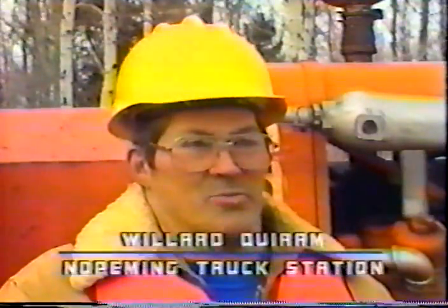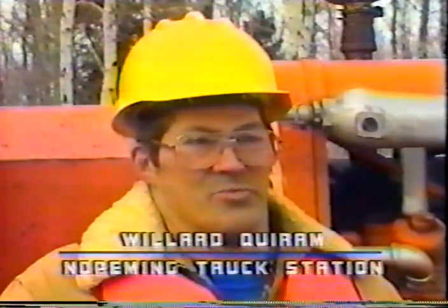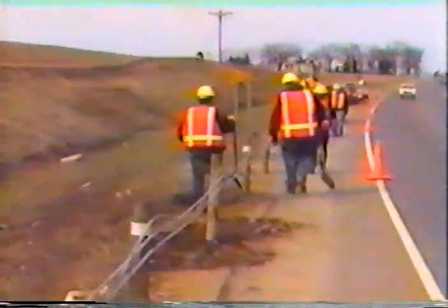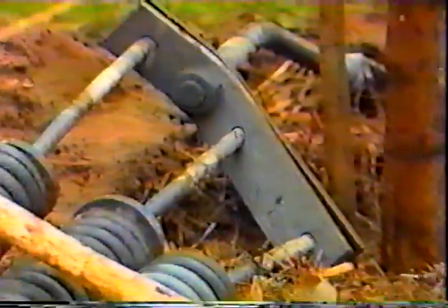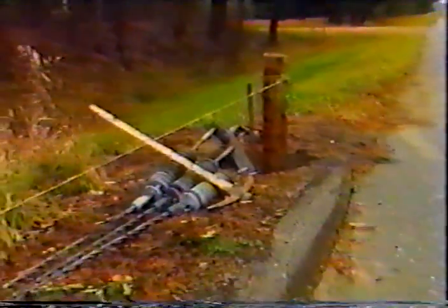If it's been weakened by a previous accident and not repaired, and I guess that's why you'd have to make sure it's repaired in that same structure that it was, to the same strength. Because if it wasn't, then you would have a weakened situation and the guardrail wouldn't be effective. That's why it's so important to walk through an entire system that's been damaged, to check out not only the visible damage, but the alterations that have occurred in different parts of the system because of the impact or impacts it has sustained.